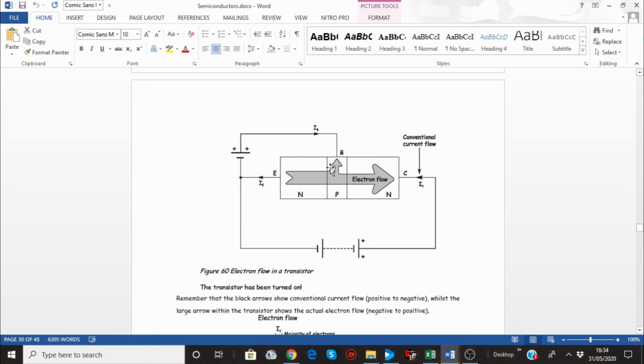The voltage between base and emitter has to be big enough to cause a flow of electrons between these two PN materials, which is a diode basically. So you have to make this a forward bias connection or configuration for electrons to come here, and then from that, the bigger voltage here and material voltage here will absorb all that instead of them all going there. Some minority will go through there, but the majority will be absorbed here.